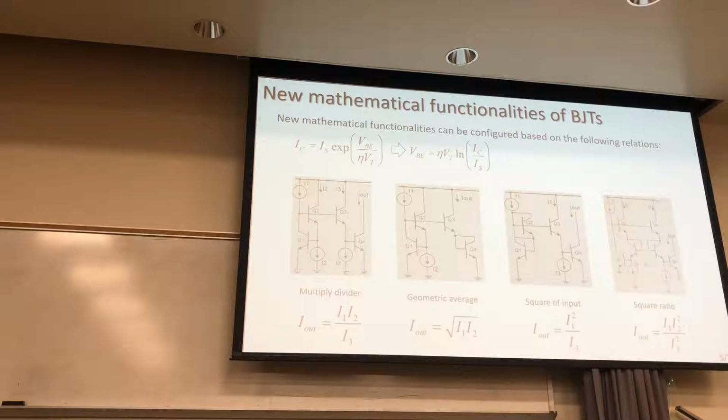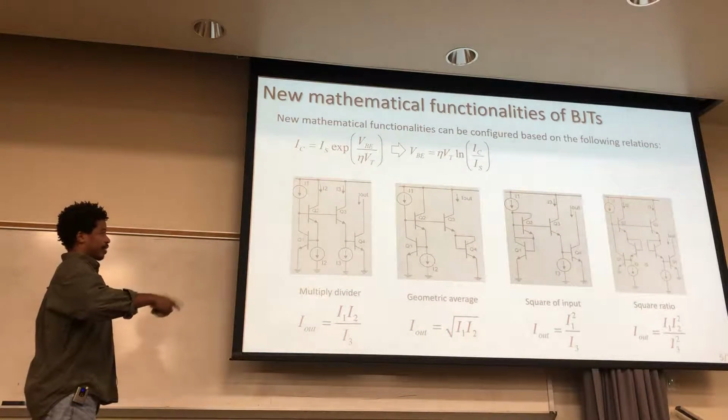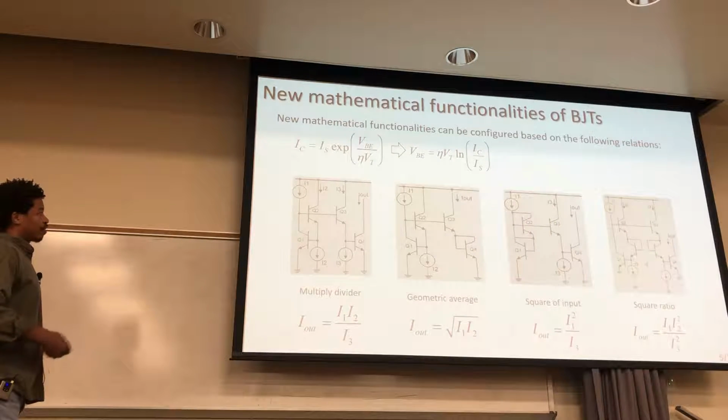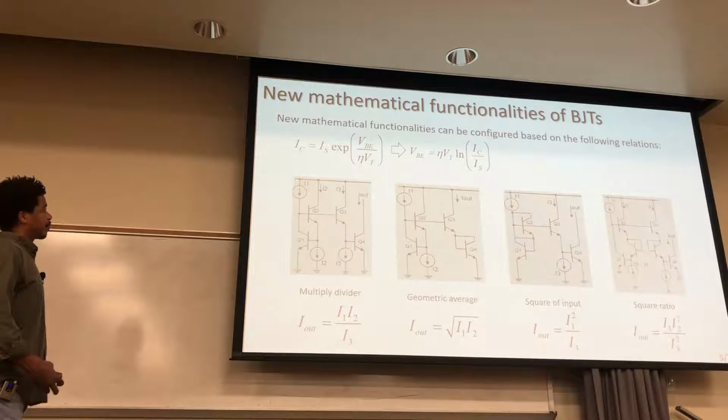But typically the converters are anywhere from 1 to even 3 orders of magnitude slower than that. Digital is very fast, but going from digital back to analog is very slow. Those conversions mess up your delay and give you latency in feeding back your signal. But if everything is done in the analog domain, you can get down to single-digit nanoseconds of feedback.